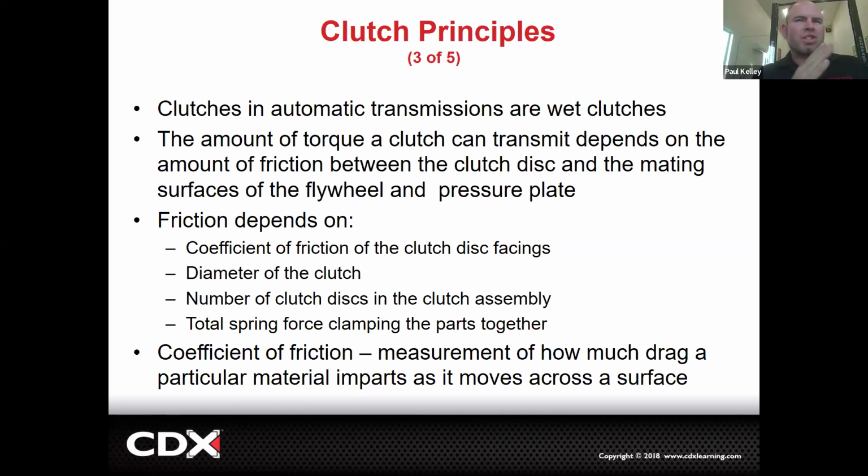Remember, progressive smooth engagement like from the factory. There was like you let the clutch pedal up and all of a sudden bang, that sucker was engaged. It was rough, it would kind of buck, and he'd be like, oh, there's something wrong with this clutch, and it was sort of like, no, dude, you ordered the race clutch. When you go with the race clutch, they're going to have different coefficient of friction. They could have different, also, they could change a whole bunch of stuff.